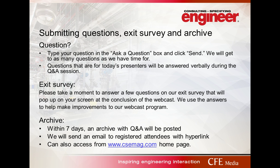Okay, there are a number of facets to that question. I think you would start with ASHRAE 170, which will define whether your room needs to be positively or negatively pressurized or has no requirement. Then you need to understand the leakage paths available. It's generally the door into, or the doors into and out of the room. Even a closed door has a crack area, which is the code term for it. Below the door, there's an air path, and maybe even at the side of the door. If there's a double door, there's an air path at the bottom, and also an air path between the two doors. So you need to do a little bit of calculation on what the expected leakage path might be, and then there's a formula for it.